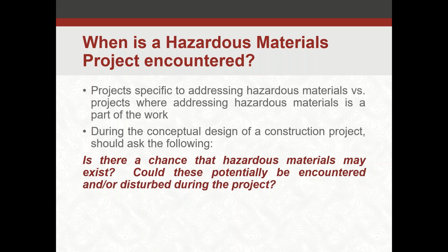Do you have a high potential to have that suspect contamination? And then from there, let's take that to an investigation phase and into remediation if we do encounter something. Not all projects will automatically look for that type of contamination, but if you do have a high risk scenario, it's usually better to plan for that and address it at the front end than to encounter it later during the construction project.